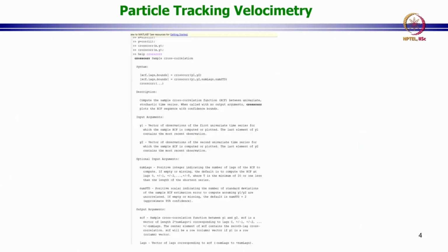So I went ahead and looked up the documentation for cross correlation. When I look it up, it tells me that I can input my number of lags right here after x and y, and that allows me to set my lag in any way I want. If you have access to MATLAB, I encourage you to read this documentation. This is all one dimensional calculation. When we speak about images, we will start to look at two dimensional calculations. Still, the one dimensional calculations give us a good handle on what is going to happen in 2 dimensions.